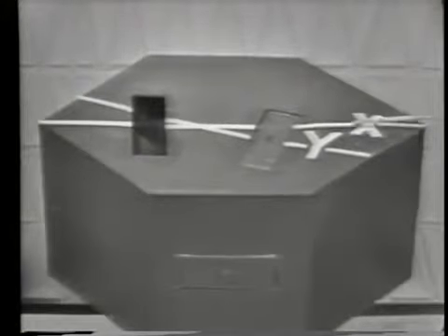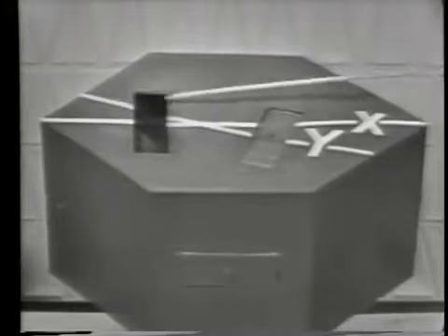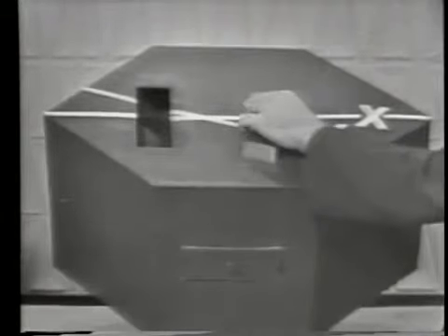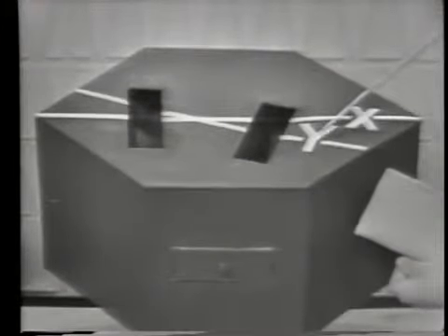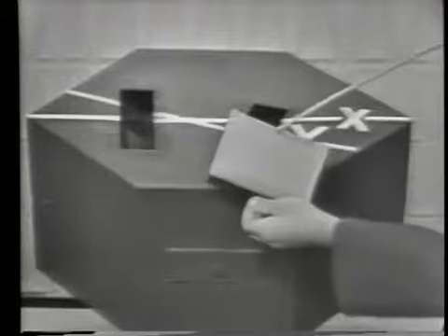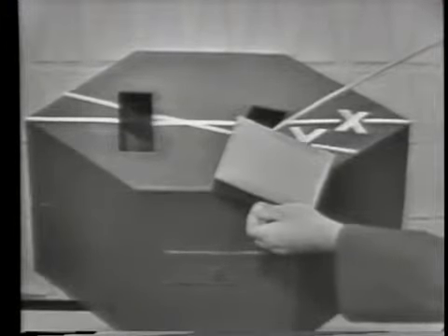Remember, perpendicular to the y, parallel to the z. And again, to get a more realistic view of this cut, let's go back to the mock-up. Remember, the y-axis passed through the face of the crystals in this manner. We'll cut perpendicular to that and parallel to the z-axis. And we come up with our second cut, which in this case, since we took it in reference to the y-axis, would be known as a y-cut crystal.